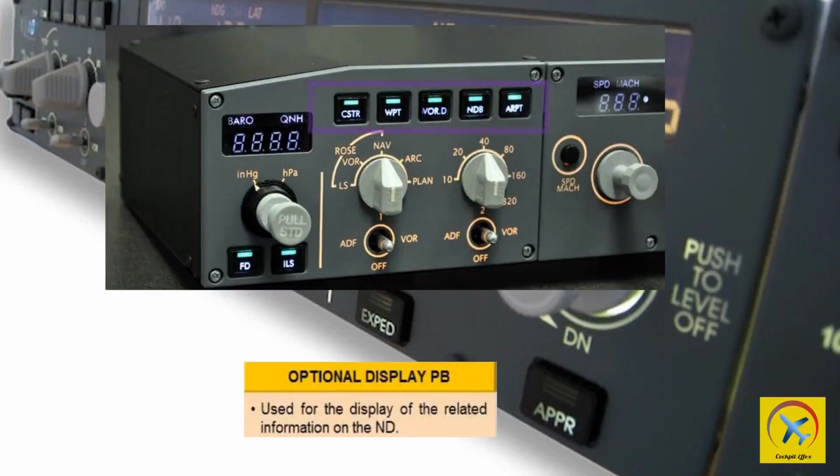When the WPT button is selected on, waypoints not in the flight plan are displayed a magenta color. The to waypoint displays white. All other flight plan waypoints display green. When the CSTR button is selected on, the altitude, speed, or time constraints are displayed a magenta color.